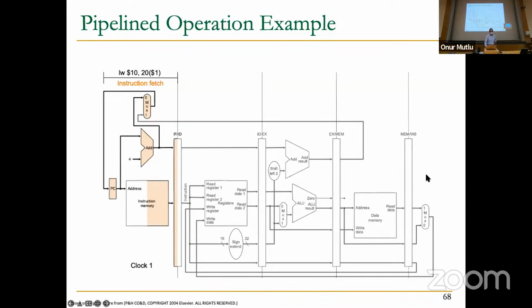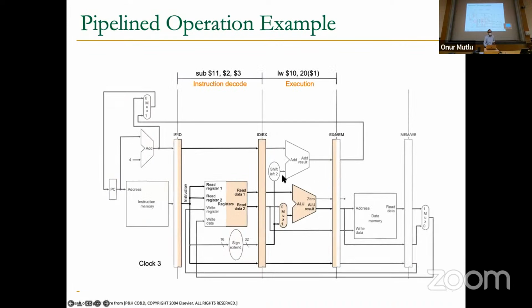Okay, so basically, what is this? In a pipeline operation, this load word has a destination register ID over here, and it has a bit saying that I'm going to write to the register. That goes to another logic over here. And then also this instruction over here has source register IDs, and it says I'm going to read source registers.